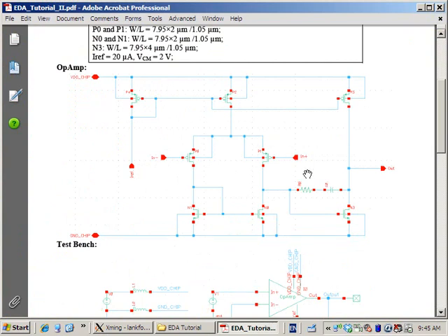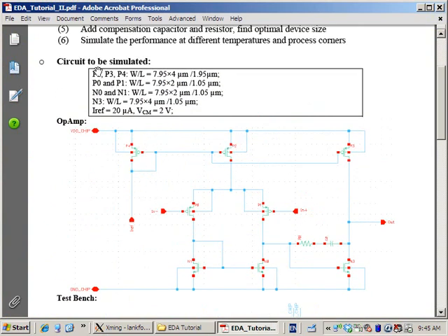So we are going to build up this amplifier, and the size of the amplifier is based on the numbers specified here. Originally, my plan was to use 1 micron as a width, but the resolution of this process doesn't allow 8 micrometers, so we use 7.95 micrometer, and this multiplied by 4 means we have 4 fingers altogether. So the total width of the transistor is 8 times 4, which is approximately 32 micrometer, and the length is 2 micrometer for this guy, and this guy.